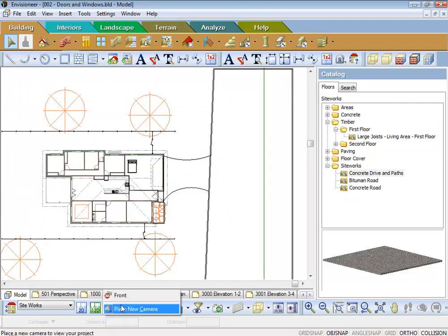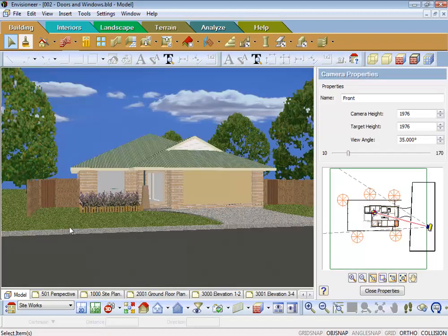Now if I go and have a look in that front camera view, now you can see my road, the curb and the curved driveway running up to the house. I think you'll find, if you remember the wall lesson, that I do say walls are everything in this program, and you can use it for many purposes. Okay, so that's the way I do my driveways, using walls and then floors by rooms to fill the shape. Thank you very much.